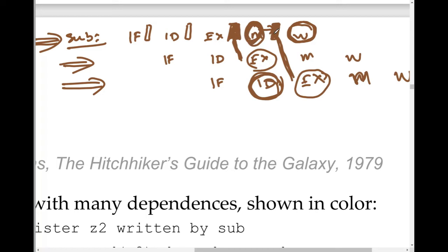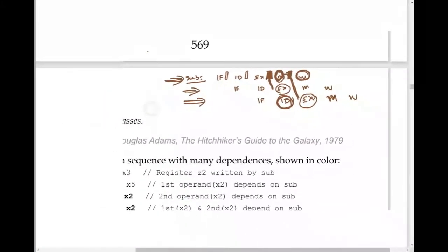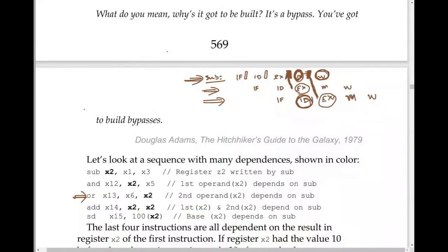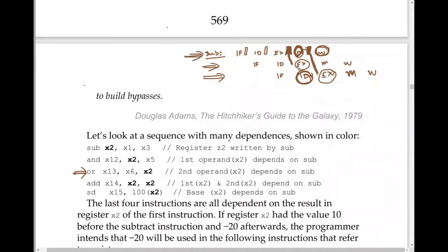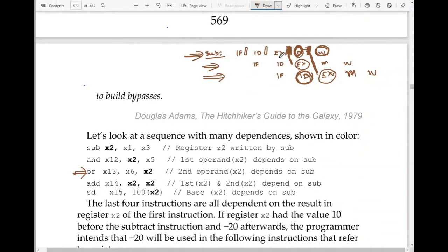If it is not clear, you can go and see the data path that I explained in the last class. Now your result value is here, so from this register you can forward it to the EX stage. In this way forwarding is also possible. So there are two possibilities of forwarding. First, forwarding from the pipeline register just after the execution stage of the first instruction, and second, forwarding from the pipeline register after the memory stage. So there are two different pipeline registers from where the data can be forwarded.